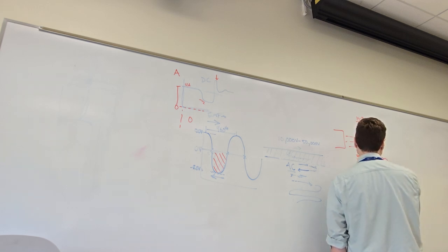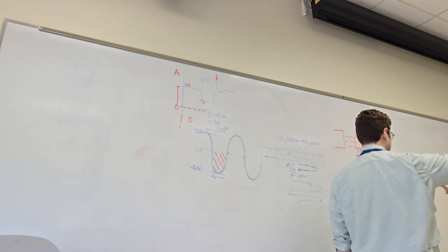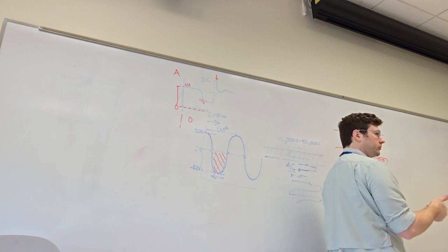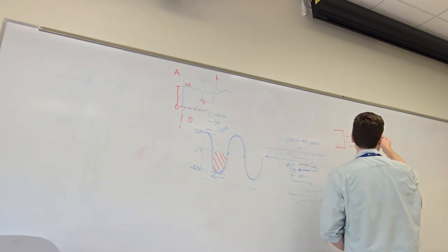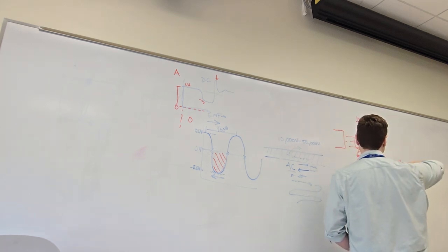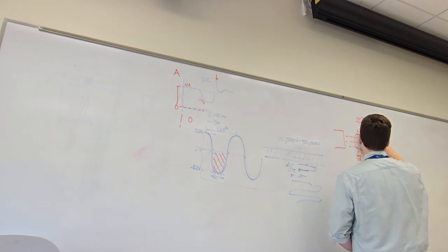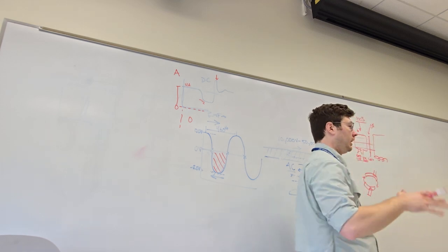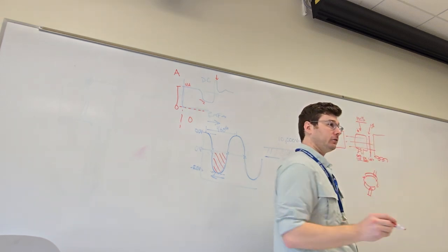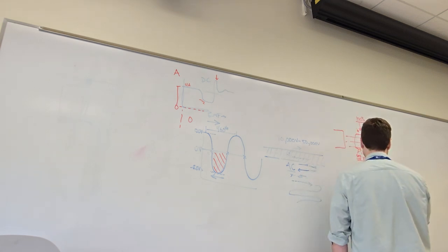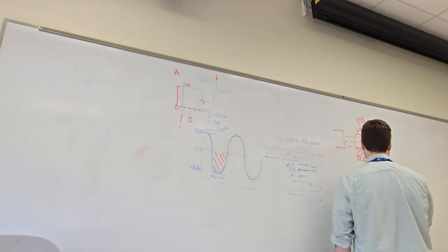As the motor turns, it swaps the polarity. So this one is ground and this one is high voltage to get it to kick over a little bit sooner, so it doesn't completely lose energy before it gets enough force to kick it back over to a relatively high voltage state again. That's what gets it to carry over that motion.